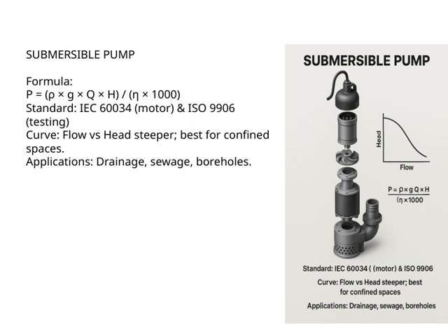It's also important to note that these pumps comply with standards like IEC 60034 for motors and ISO 9906 for testing, which ensure quality and performance. When looking at the pump curves, you'll see that the flow versus head curve is steeper compared to other types. This makes submersible pumps particularly effective in confined spaces where space is limited, but you still need reliable performance.